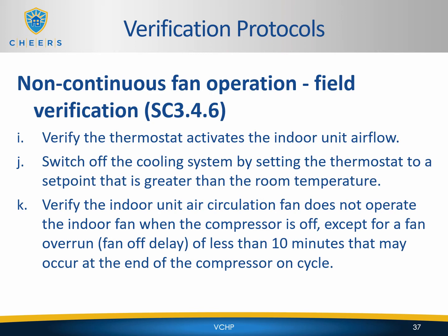So it's just a quick summary. You're going to turn the heating system on, make sure the fan only comes on when the heating system's on and then turns off once you turn it off, and do the same thing on the cooling cycle. You just want to verify that the fan only runs when either the heating or the cooling system is actually running.